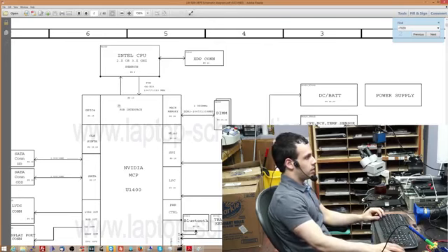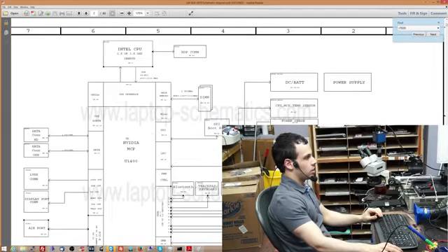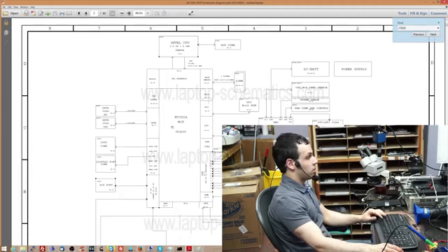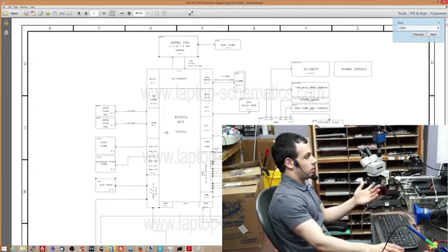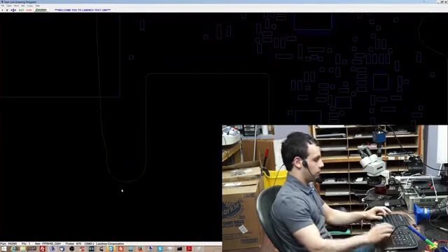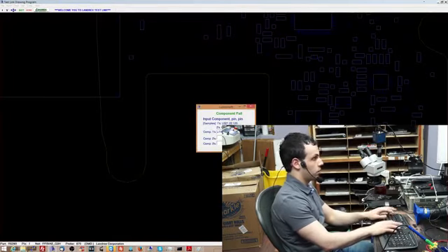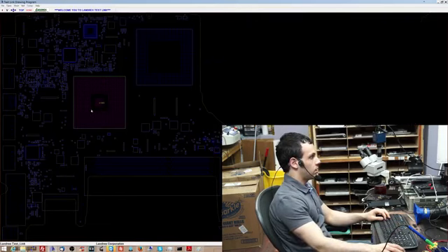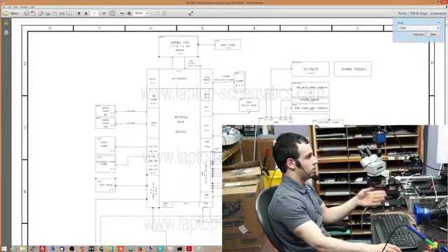Here is the beginning of it, where it tells me how everything talks to one another. It tells me what chips are responsible for different things. One of the things that's great about a schematic is that it helps reduce ignorance. For example, a lot of people are calling this a GPU. This is U1400 inside of this 2010 motherboard. They call it a GPU. It is not a GPU. It is an MCP. It is not simply a graphics chip.